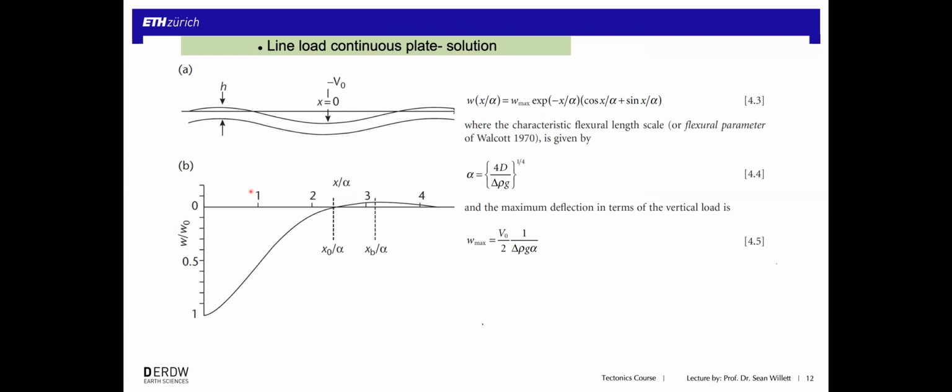And the shape of this is right here. This is now, unlike these little sketches, the true solution to a continuous plate under a line load. It goes deep, comes up. We have this flexural bulge that comes up above the datum, then it goes back down again. It's only plotted to here, but in fact, it oscillates a few more times infinitely. It's a sine cosine function, but the amplitude gets smaller and smaller because of the first term. So we typically ignore everything from about here outward.